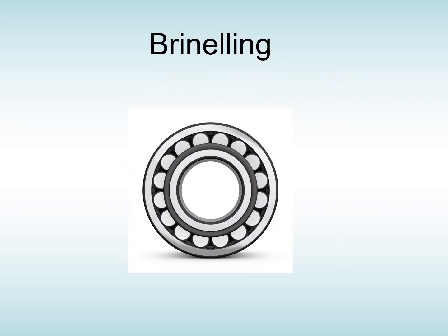Brinelling. So this is what happens to bearings when they're left and not moved, on a compressor, etc. that is standing idle for a long period of time. You've got the load of the shaft pressing down on the top, and you get these little tiny points of contact. And if there's any vibration in the room, these are going to chatter up and down.